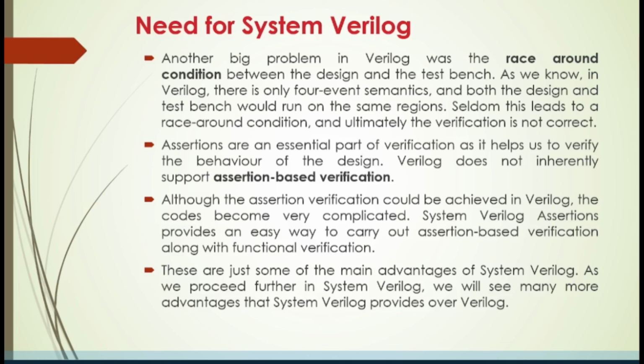Now you can have a doubt: ma'am, we have already discussed the race around condition in Verilog, and you told us that by using non-blocking assignments you can avoid it. Yes, we can avoid it when you are assigning the same value to different variables, by using non-blocking statements.